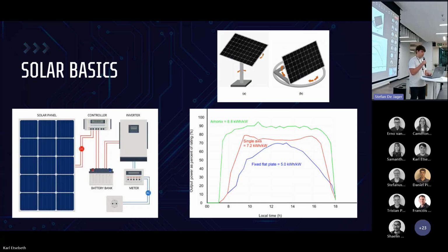MPPT stands for maximum power point tracking, and it's a bit beyond what I'm going to cover here, but essentially it helps maximize solar panel output. The DC from the battery is then converted to AC via an inverter, so that's shown there. Inverters make use of high-speed switching circuitry to mimic a sinusoidal output before passing it through filters for smoothing.